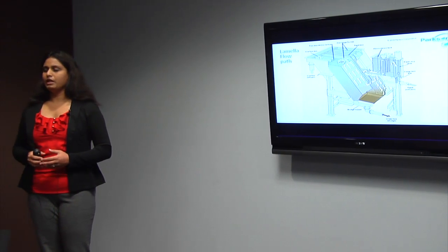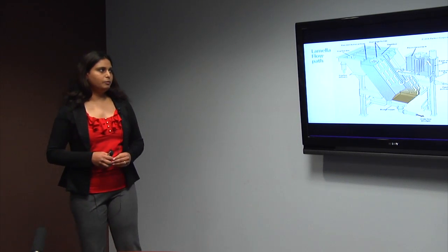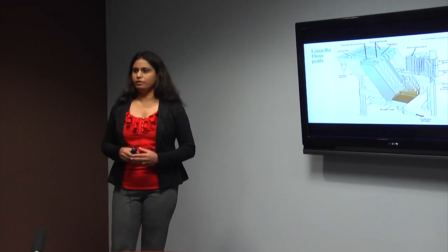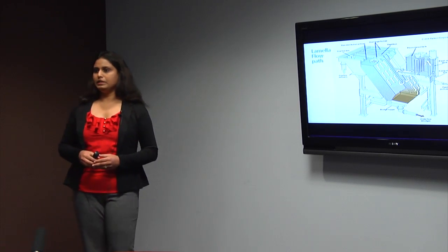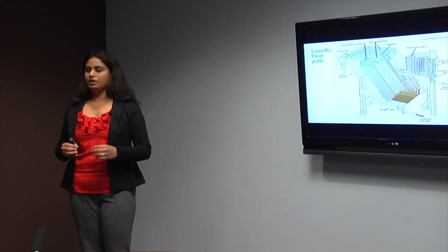The flocculation time can be dependent on the application. If it's a surface water type of application, potable water type of application, then you would need up to 30 minutes sometimes. So the flocculation time purely depends on the application. If the water has less turbidity, then it would require more flocculation time, because you need more time for the smaller particles to come together and become bigger particles to settle down.